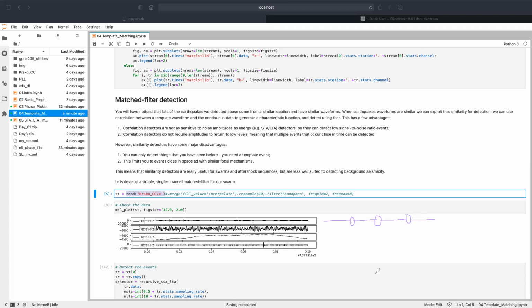There are many ways you can do this. One way is to just put zeros in these holes. But then when you filter the data, you can get some problems with strange signals. If you filter something with zeros inside, the filtered signal will look like this. So it's better to maybe not use zeros. You can use it with 1, with anything, but then your signal might look like this, which is, again, not something we want.